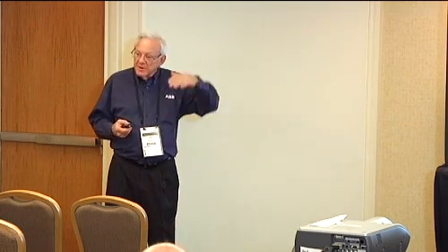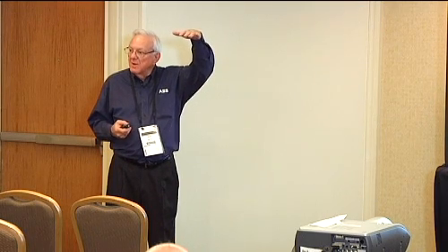That little box is for 2,000 and 3,000 amp breakers because I have a vent above that so I can let the heat out. But as soon as an arcing event occurs, that same vent has got to shut down. Up on top, there's a shutdown louvering system that stops everything, and I got to have a reset, and that's why this thing continues to go up.